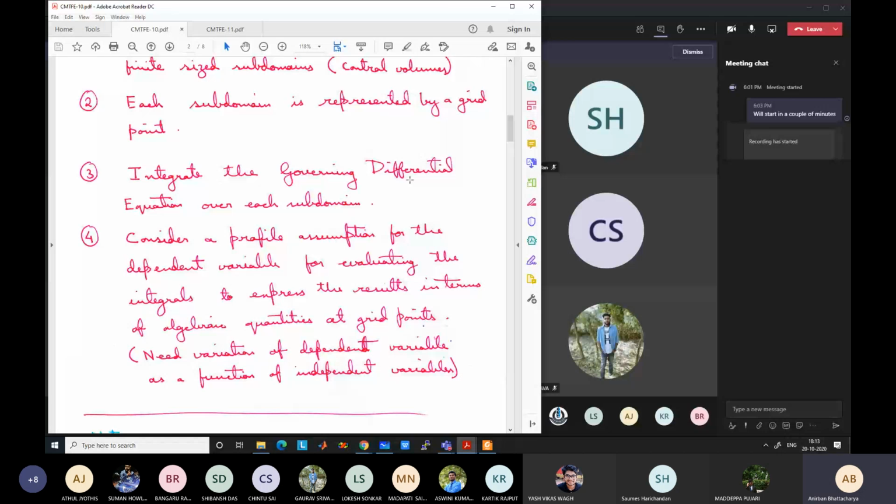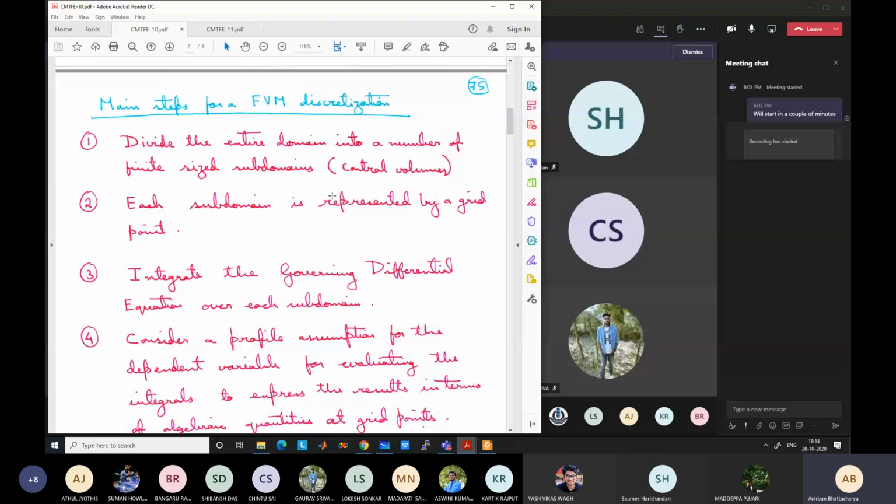Similarly, there is another method, the finite element method, which we have not discussed much because it's not used much in the CFD process, as it is much slower compared to finite difference. The finite element method is also a method of discretization, which is generally used more for structural problems, as you know. There too are control volumes, called elements, and grid points, called nodes, but each element might have multiple nodes, and some functions are used to represent the properties within the elements.